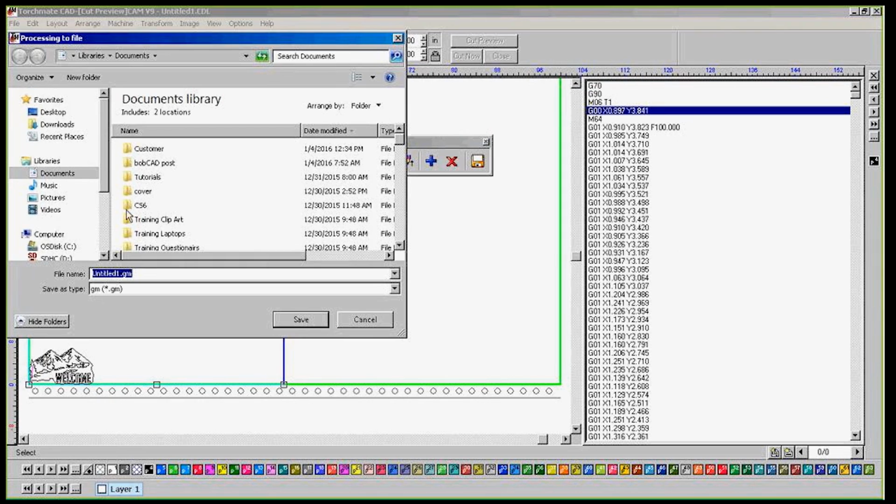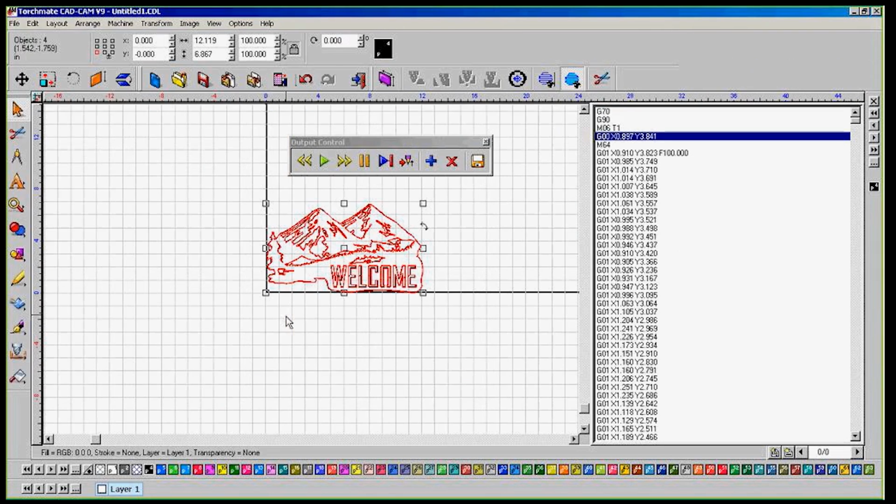No, absolutely, and that is a great question. You can generate straight lines, and you would use the online toolpath instead of using a male or female toolpath instead. So if you have some fold lines or some other details, or I know there's a lot of clip art out there that does have just straight lines that aren't actual shapes, then you would want to separate those from your design and select them and do an online toolpath for those items.